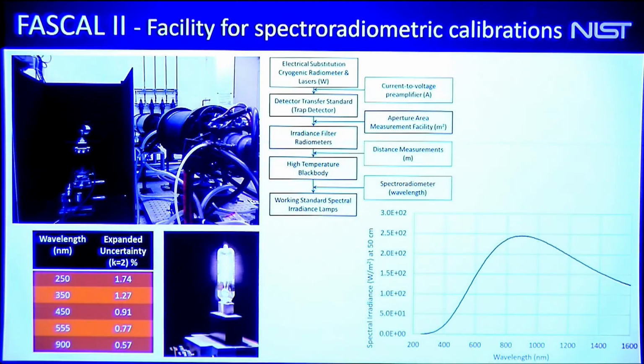They take some sort of black body, shown in the upper left-hand picture, with electricity going into this cavity, and they take it up to about 3,500 degrees. It puts out a black body radiator curve, shown in the lower corner. I can measure that absolutely, and it'll follow the black body curve, and then I can calibrate that signal against lamps and disseminate it that way.